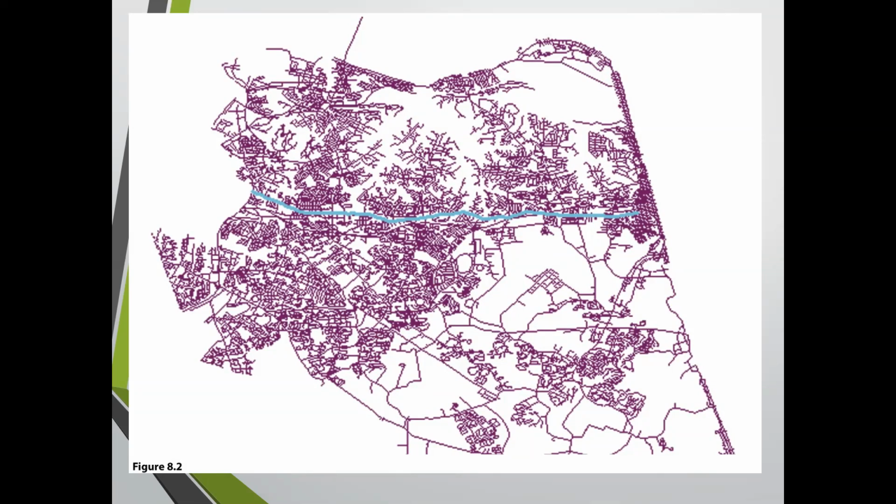All right. The other thing to think about too, and this is really important, is that this picture was produced, who knows, let's say maybe in 2005. Now we know, because we're involved in the building activities, especially things like subdivisions, that it's constantly changing out there. Roads are constantly being added, roadway networks are being added. So this might be way outdated, and information can only be utilized from what's in this database. So we have to constantly update these base maps to be able to have a valid picture.